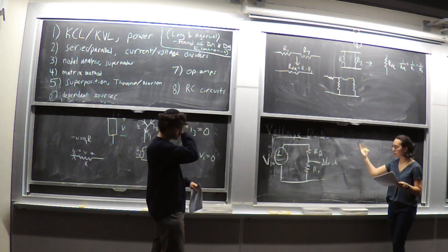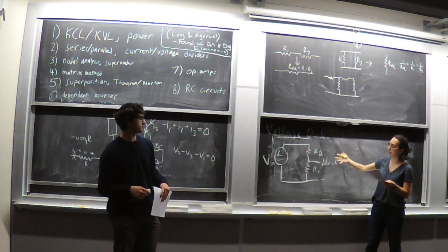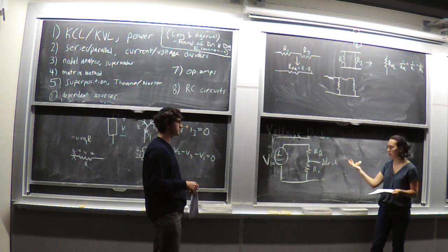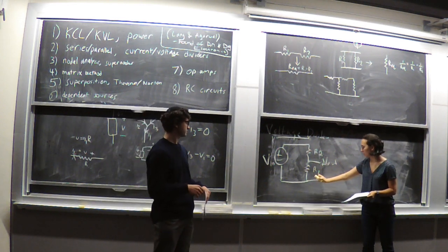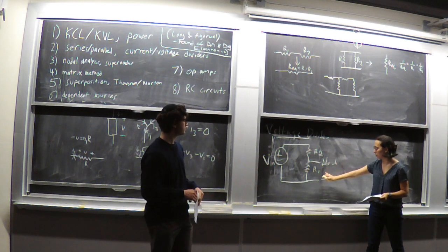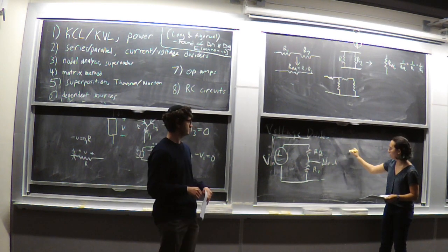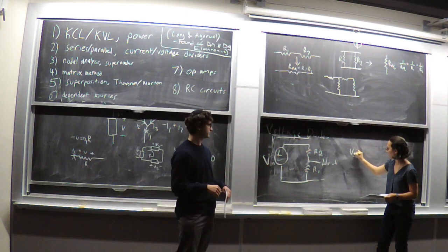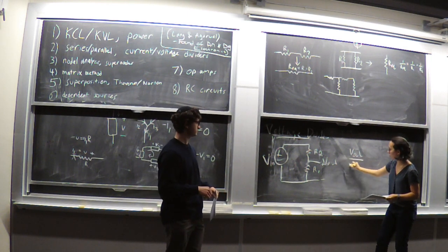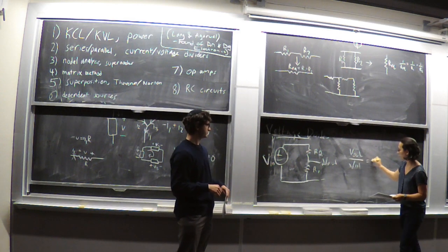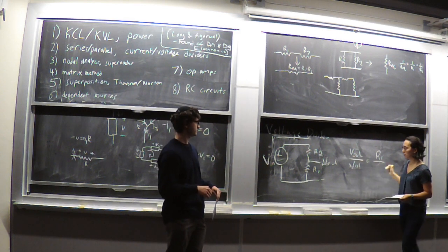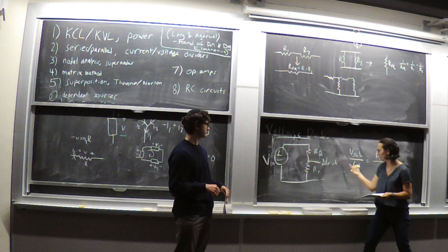And we know intuitively when we see this, because we can derive this just from using the fact that these resistors are in series, in particular, the ratio of the resistances. The fraction of V in that we get as V out would be R1 over the total resistance that V in sees, which is R1 plus R2.